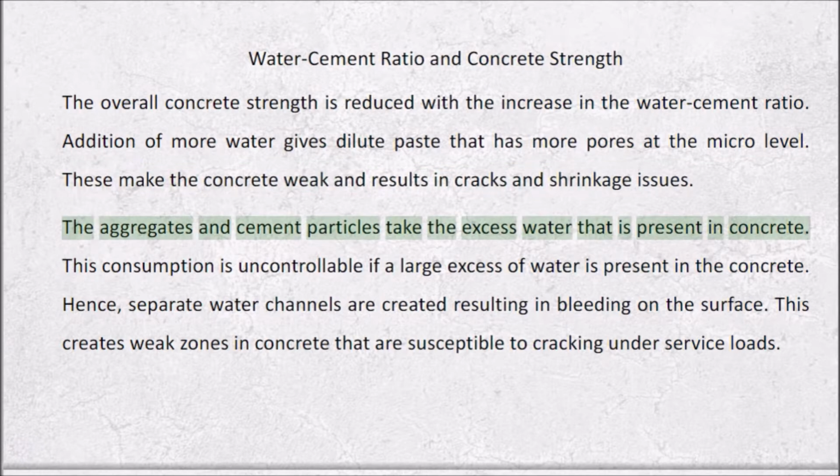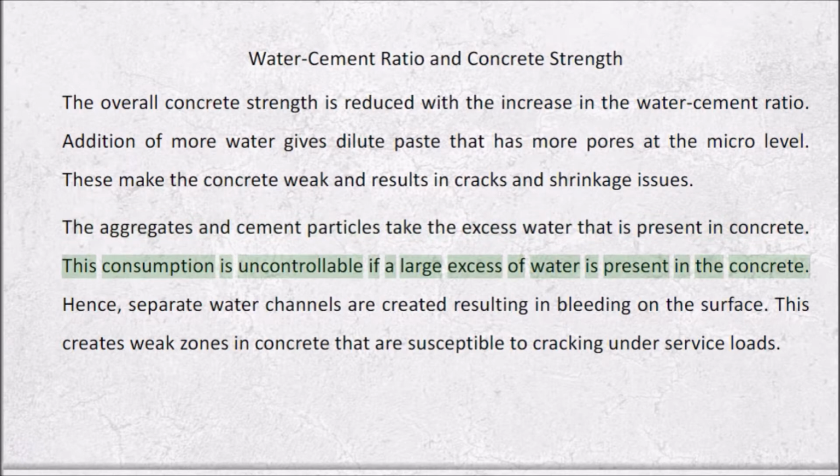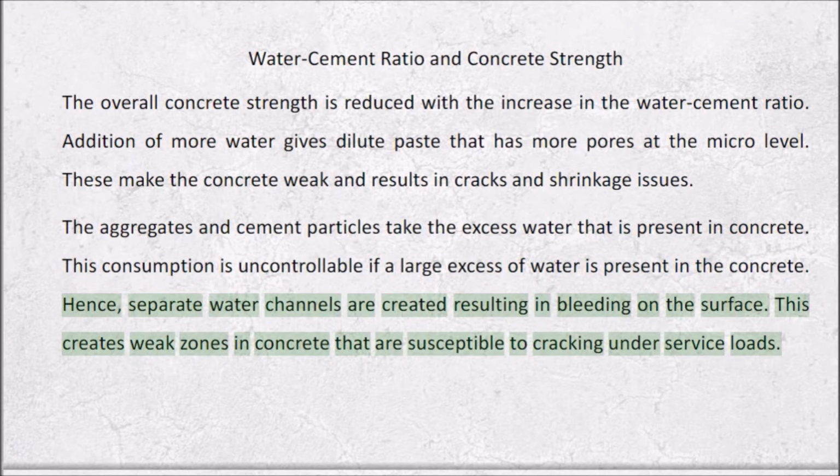The aggregates and cement particles take the excess water that is present in concrete. This consumption is uncontrollable if a large excess of water is present in the concrete. Hence, separate water channels are created, resulting in bleeding on the surface. This creates weak zones in concrete that are susceptible to cracking under service loads.